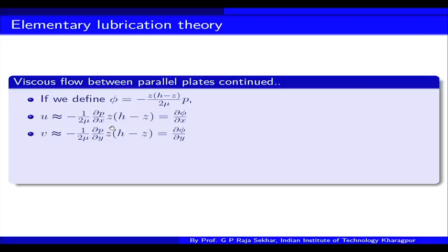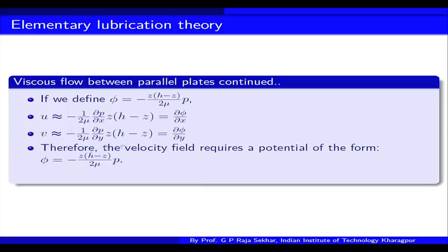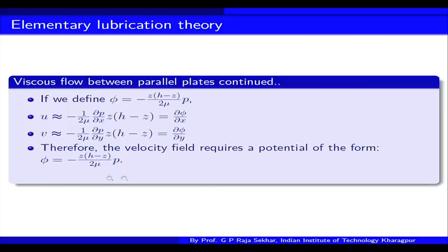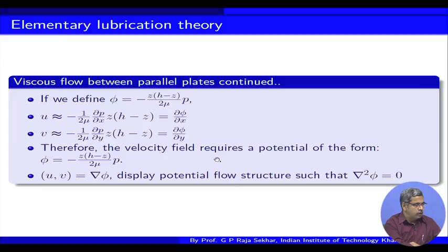So, this I have explained. So, we got the corresponding velocity potential, which is given by this, right. Now our aim is to get the equation satisfied by phi. Once we have the divergence free condition, then phi is harmonic, which means under lubrication approximation it is enough to solve a harmonic function, instead of solving the complete component equations. That is a great achievement.